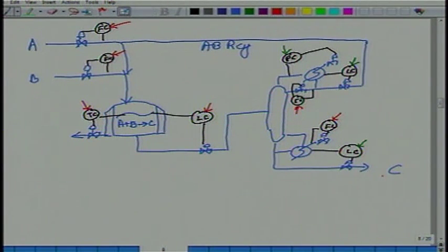Then he gets irritated every time I have to look at the quality and change the steam. So he gets a little smart and he says, well, I will put in a temperature controller that sets this set point. Because the management was not happy with what he was producing, its quality was not good, okay. Once he does this, what happens is, because you are putting in excess amount of B or A, whatever be the case, which was dropping down the bottoms, now the temperature controller does not allow it to drop down the bottoms,